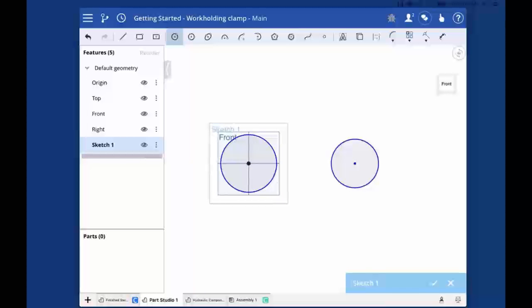And tap a second circle. So now I've drawn two circles, one on the origin, one just horizontal to the origin, and they are constrained that way because I used the precision selector. Now, you can just start tapping circles in space, and some do and then decide to constrain them later. But realize that if you tap and hold, you get that precision selector, where you can move over and very accurately select things.